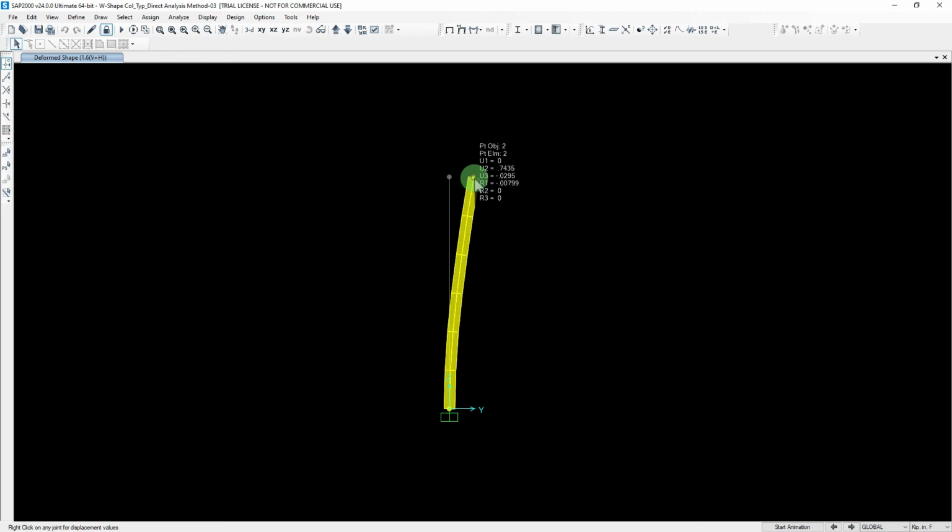All right, so now we have a deflection of about 3/4 of an inch in the lateral direction versus what was about 1/8 of an inch the first time. We might even think that if you didn't know, an inexperienced engineer would say, oh, I have a very small deflection, and this thing is actually multiplied by the 1.6 factor. Okay, that would be completely incorrect. All right, so this is where it pays to understand what you're doing.